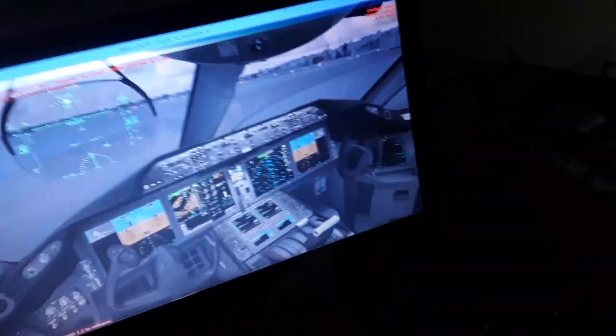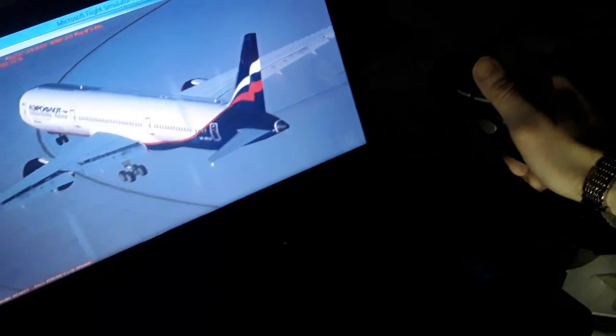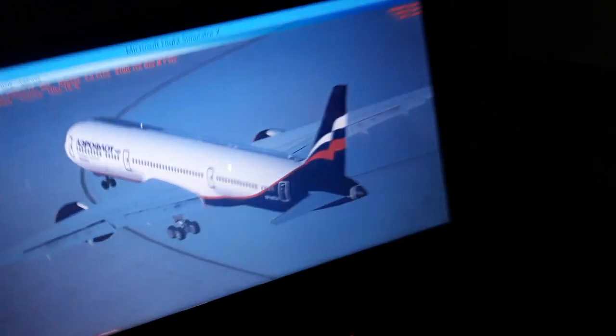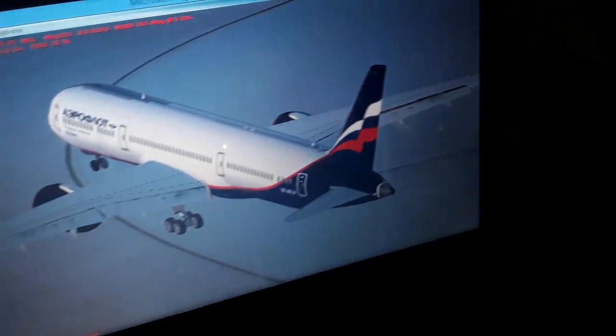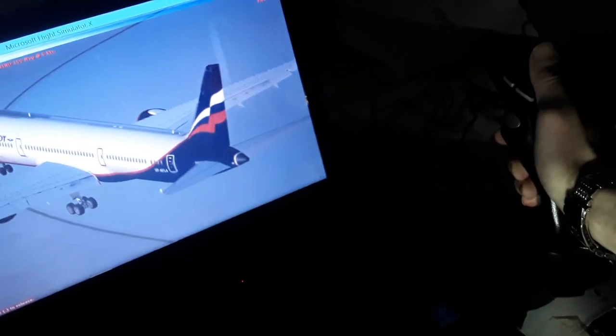like this. So this makes ailerons and spoilers in the Airbus, side stick left and right, or aileron, spoilers and flaperons in the Boeing. Using the Boeing right now, using the control wheel, make left and right turns, the pitch up and down side stick, and the rudder pedals.